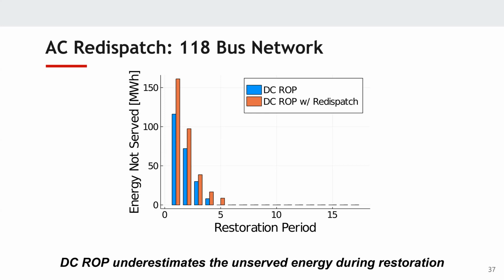It could have been that the next repair was several repairs down, and then there's this trade-off of, while we are able to even solve this with a DC formulation, unlike with an AC formulation, it's not clear that this will give a very good solution all the time. And this redispatch will ensure feasibility, but it's not an assurance of a good solution every time.